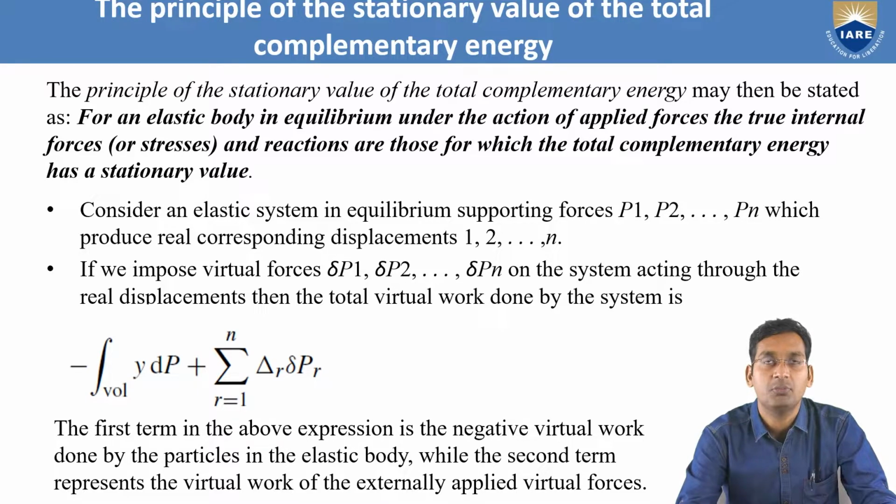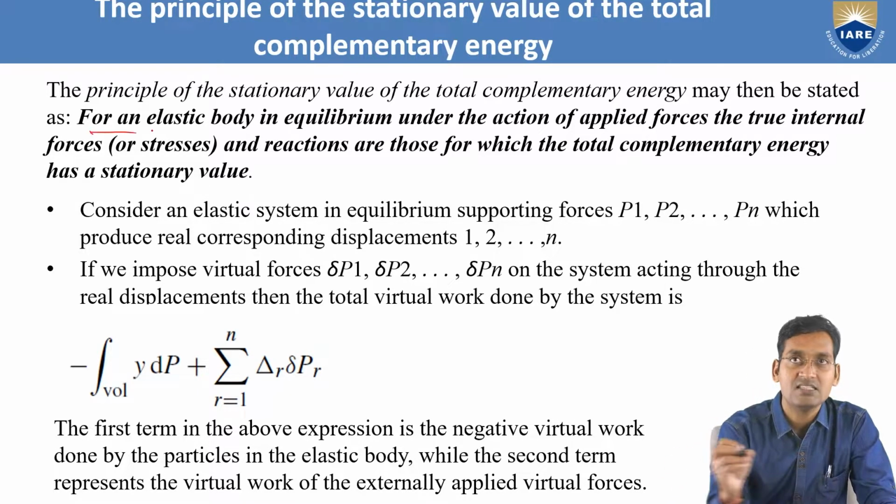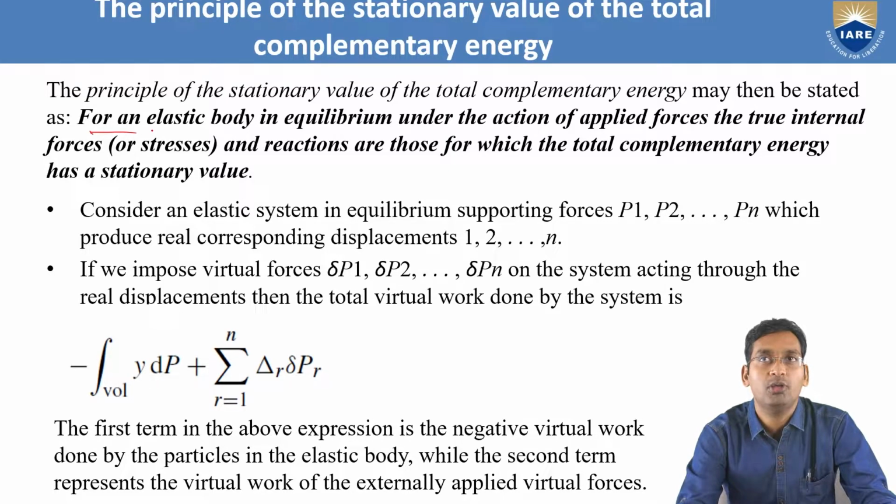What is that principle? The principle of the stationary value of the total complementary energy may be stated as follows. For an elastic body in equilibrium under the action of applied forces, the true internal forces, either force or stress, that is force per unit area, and reactions are those for which the total complementary energy has a stationary value.